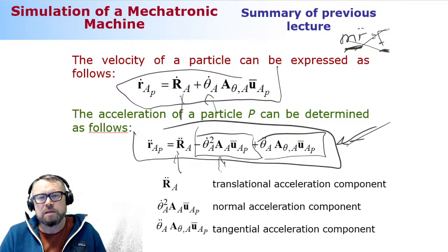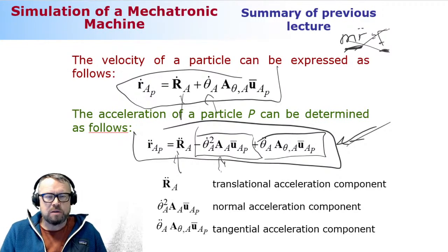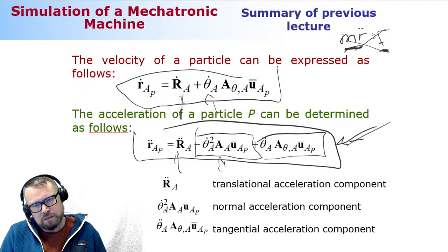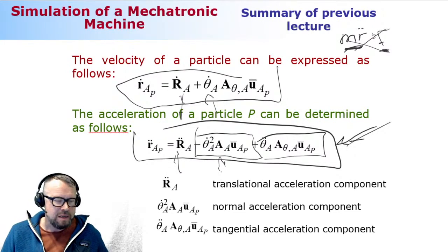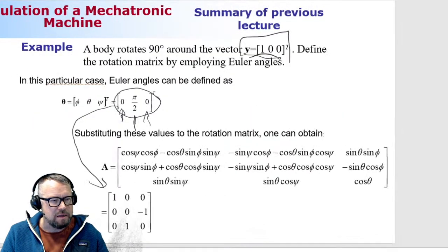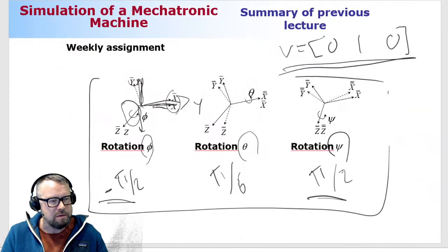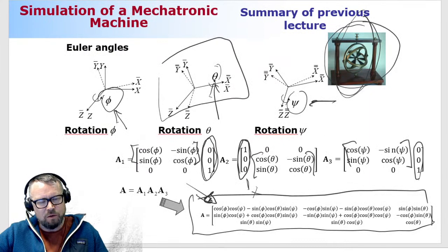Can we use another sequence of rotation? Yeah, you can, that's okay too. But then you need to derive this rotation matrix by yourself, which is possible too. To make it easier, I recommend you follow what I just explained. Because if you change the sequence of rotation, then this matrix is no longer as it is written here.